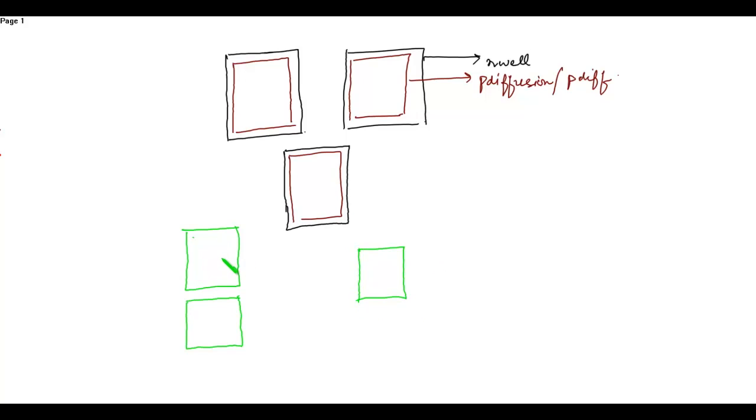So the NMOS N1 and N2 are in series with each other. Together they are in parallel with the NMOS N3. Okay, so this is the N diffusion layer. When you write the command, you will write it as ndiff.